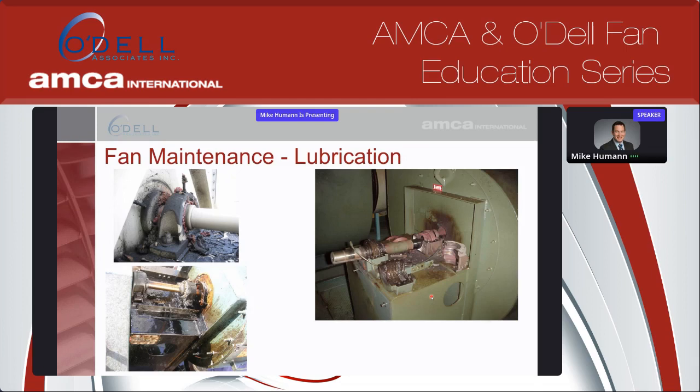You can see in the photos on the left-hand side, we have over lubrication issues. When you lubricate a fan, that first lubrication, when you inject that new grease in there, the bearing actually heats up a little bit, and it'll start to dissipate heat as that grease breaks in. That's something you want to watch as well. If it's retaining heat, then you might want to start looking for some other problems. On the flip side of that, under lubrication is obviously an issue as well. You can see there's a fan example here that burned up some bearings due to lack of lubrication. So you really want to find that happy medium when it comes to lubrication.